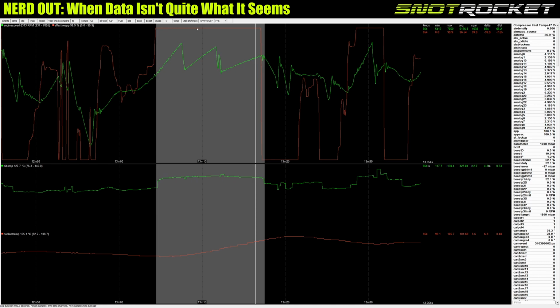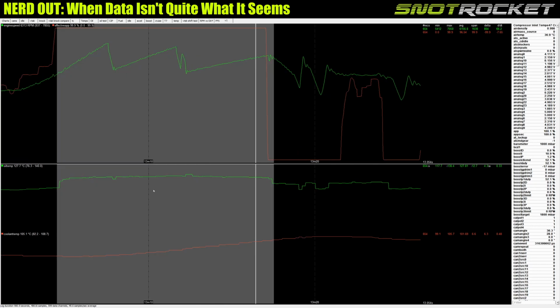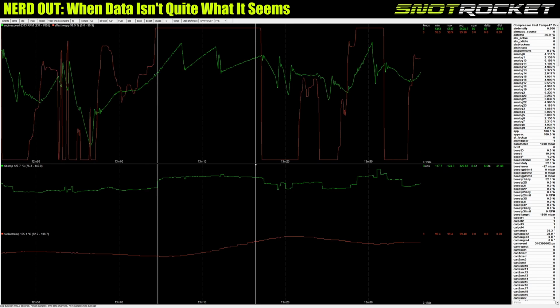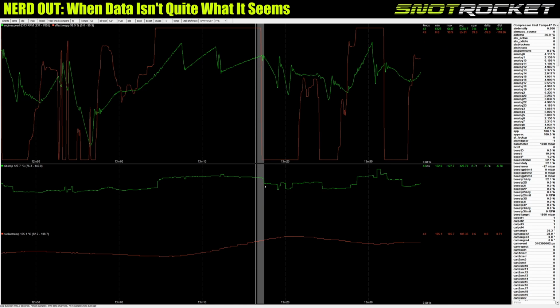And the throttle was flat out, so I'm using flat foot shifting. I'm hard on it down the straight at Snetterton. But whilst I'm hard on it, this oil temperature has just gone up. It's just shifted up instantly. If we go here, this little spike here, which is about a sixth of a second, has gone from 117 to 124 degrees centigrade. But then, interestingly, as soon as you lift the throttle here, I'll highlight that, the oil temperature drops by a similar amount instantly. And that's just not realistic.